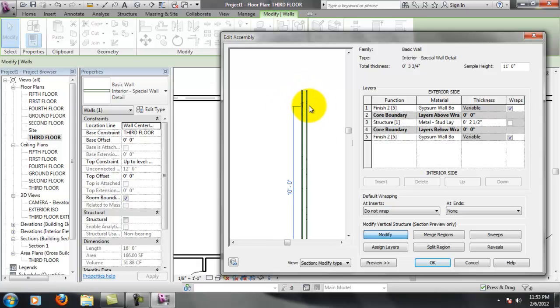The ceiling's going to drop down, but we'll keep it at 10 feet for right now. The bottom of the deck is right here at 11 feet, which means there's going to be a drop ceiling that comes down for plumbing and electrical work, which is probably going to be about 1.5 to 2 feet. So really the ceiling is going to drop down here, so really this line needs to be further down. We'll calculate that here in a second.